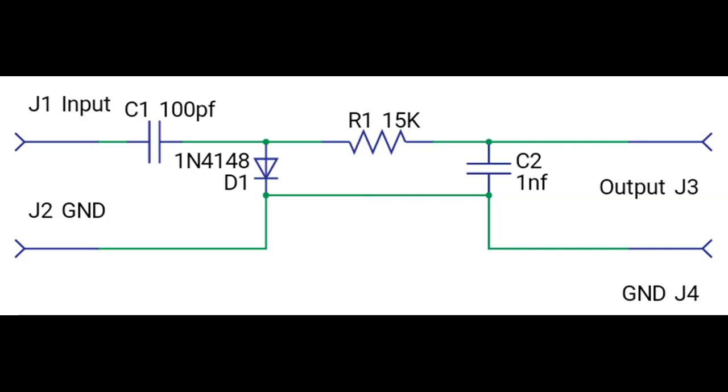I put this together, and it loads the circuit slightly, but about the same as the T4 does, because you can't touch the circuit without doing some loading, but the other one, just using the plain coax, was dropping it right down. So this does about the same level as the T4 did, and with no distortion.